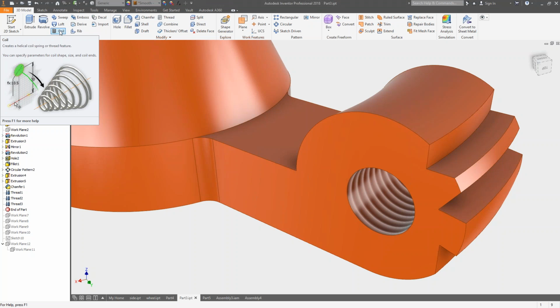The only time you would do a real helical cut for a thread is if it was some kind of oddball custom thread and you needed to generate the code for that for some CNC toolpath. But other than that, I'd watch doing helical cuts in real threads, unless you're just doing a cool rendering. Sometimes you do it just for a picture, but for production purposes, I'm gonna kind of caution you against it.